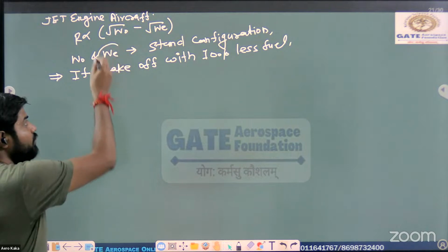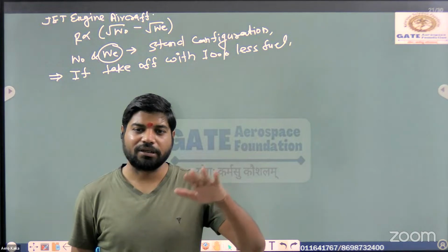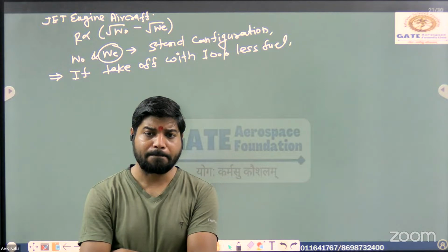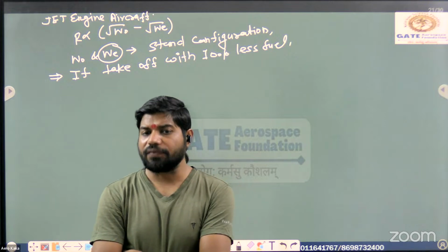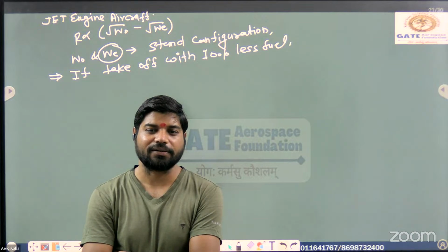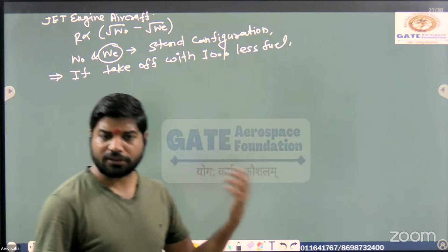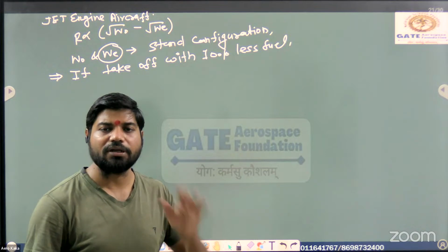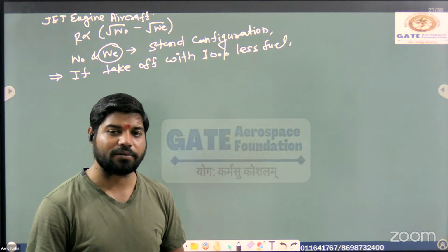Is there any change in WE? If this aircraft carries 10% less fuel, then which weight will increase or decrease, or which is the function of this WF? Obviously W0 only, right? Whether it is carrying 10% more fuel or 10% less fuel, the value of WE is not going to change, right?